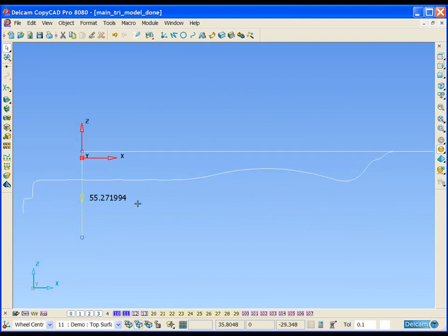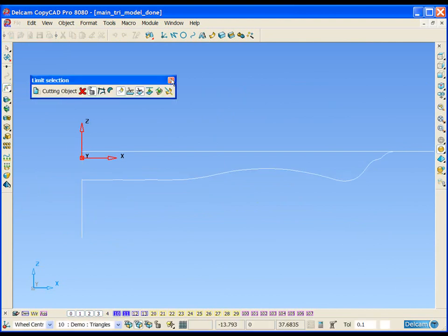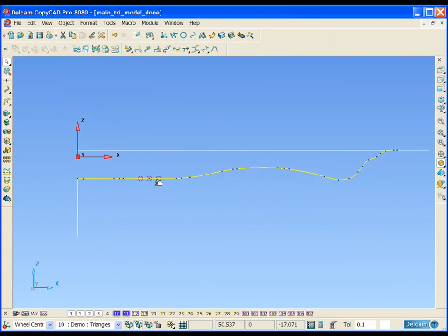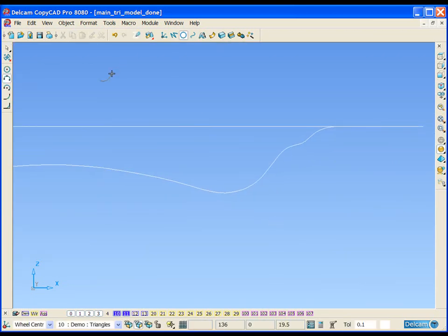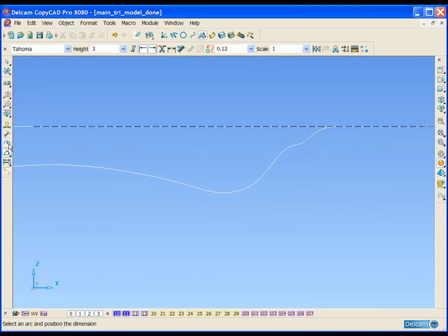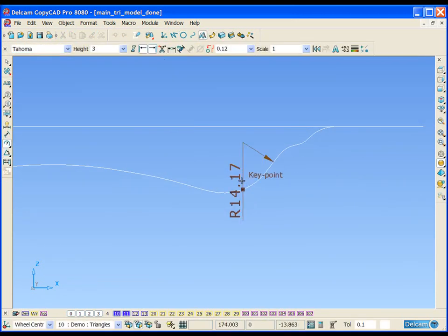First of all, using our design constraint wireframe, we can limit back our piece of cross-section wireframe. And if we select the wireframe that is a cross-section of our scan data, turn on curvature shading, we can see that the curvature of this line is not uniform at all. You will also see, if we take some measurements, that the radiuses involved in the creation of this curve are not round figures.